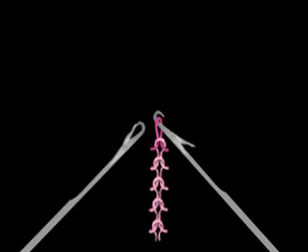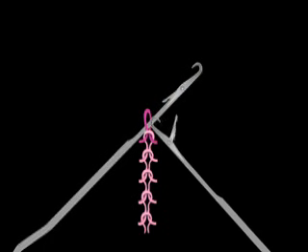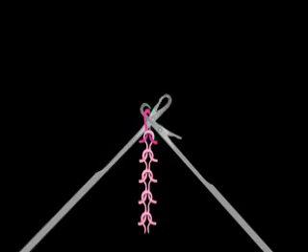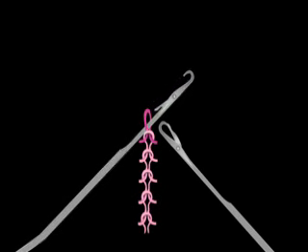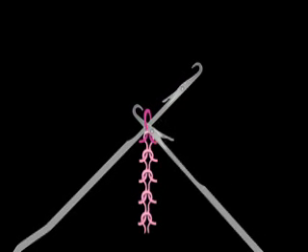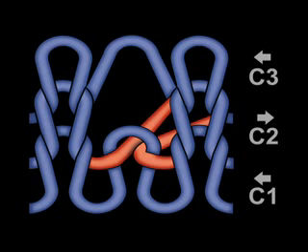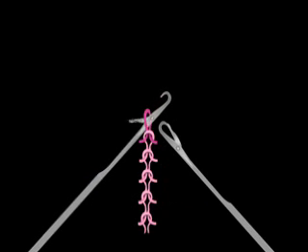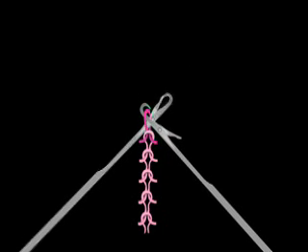The 2 most common transfer stitches in sweater knitting are to either transfer from a needle in one bed to a needle in another bed, or to transfer between 2 adjacent needles in the same bed. If the stitch is transferred between beds, it is called rib transfer. In this illustration, the red loop has been transferred from the back bed to the front bed. After transfer and during subsequent knitting cycles, a new yarn can be added. The transfer stitch will result in an opening in the fabric.